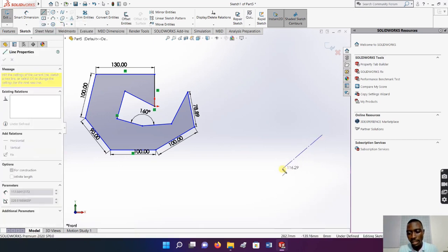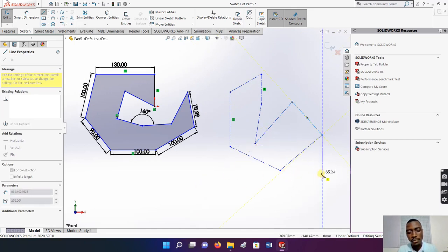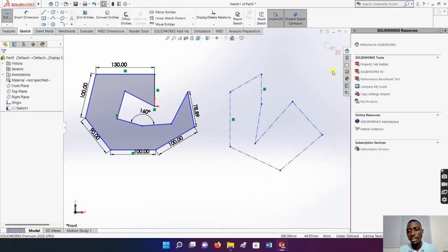I can do it this way, this way, this way. It can equally do all that the line can, but center line has no end even if you close the drawing. So you just have to click the select tool or the escape on your keyboard. This is center line, and it is not a closed figure because it is inactive. It only helps you in your constructions.